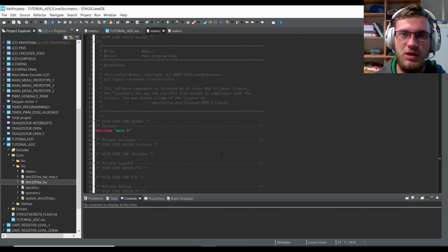I will now describe how I want my program to work. I want to configure the ADC to trigger on some sort of interrupt event and to do a single conversion. I want the interrupt event to occur every second. For this, I will use a timer. The ADC will be configured so that it will start a conversion only on a rising edge. So the timer every 1 second will generate a rising edge, and therefore the ADC will know that it must